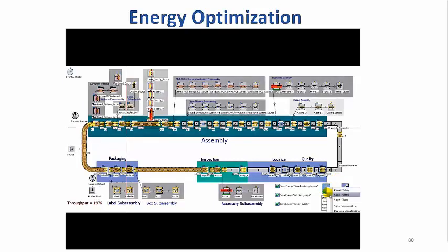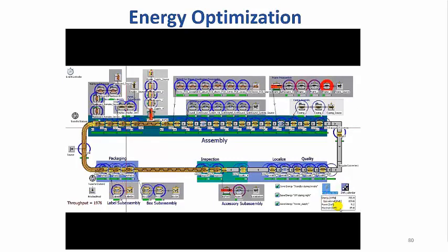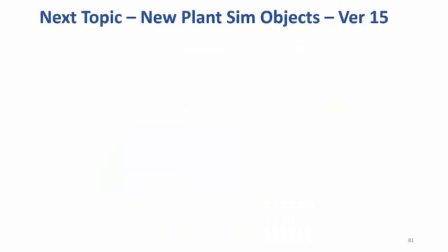Finally, if we take another look at the Energy Analyzer's Show Visualization option, we can see things have improved dramatically in the power supply area. Instead of solid red circles indicating high energy consumption, power supply stations 1 and 2 are now purple, indicating a medium level. There is room for even more optimizations, but I hope you've seen enough to see how useful Plant Simulation's new energy optimization features can be. I hope you appreciate the value of those new features.